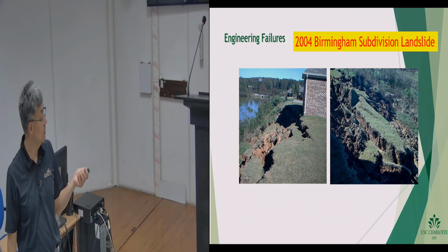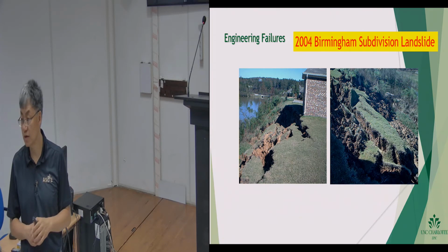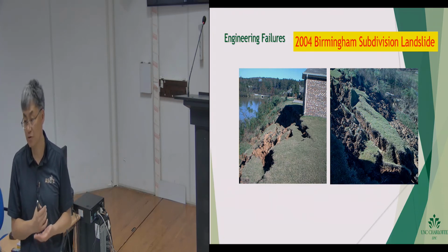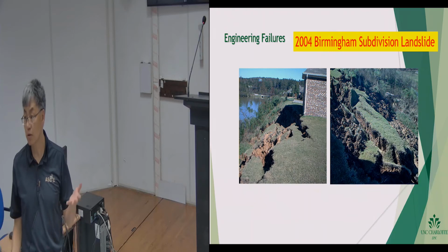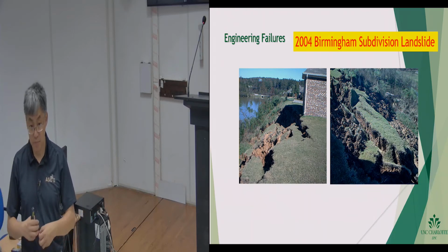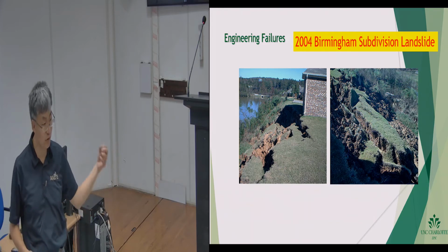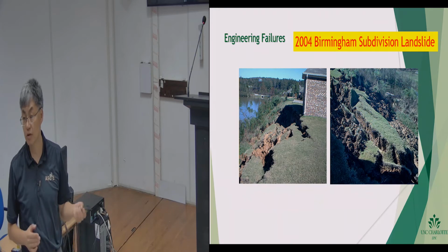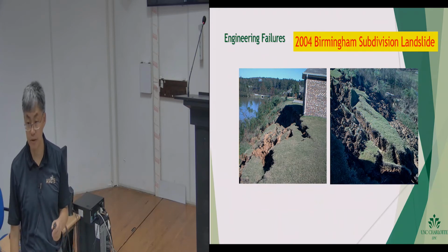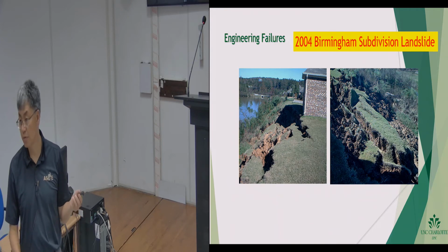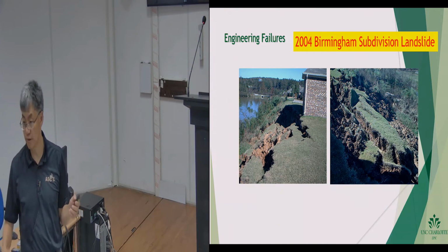And then it was at that time we see multiple homes. Then we start realizing that the problem is much bigger than just poor compaction of the ground. The groundwater had actually fluctuated because of the draining. People have to build new homes, they drain the groundwater and they change the water path, and so you result in multiple homes failing. So it quickly becomes a very big lawsuit against multiple members.